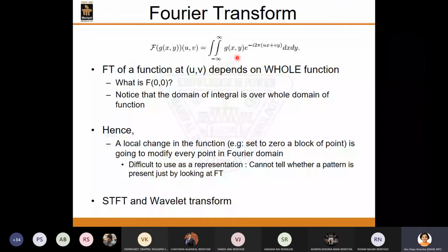Okay, and in such cases, if we have to represent a particular image where we need information of the frequency changes, but at the same time where exactly is the spatial location of those changes, then we go ahead with techniques or transforms like the wavelet transform. But Fourier transform is preferred when you know what noise is present in the image and what exact frequency of the noise is present in an image.